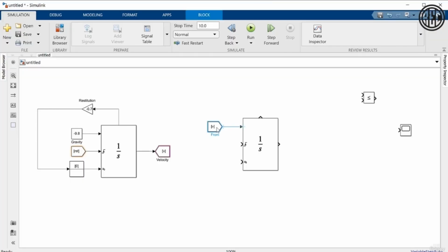All right, so again, we're doing the same thing here. The integrator, this one over here, is what we're going to use to get the position. To get the position, we have to integrate the velocity. So we're feeding the velocity from here to here. Now we're going to have the same reset, so every time the ball reaches 0, we're going to reset our calculation.